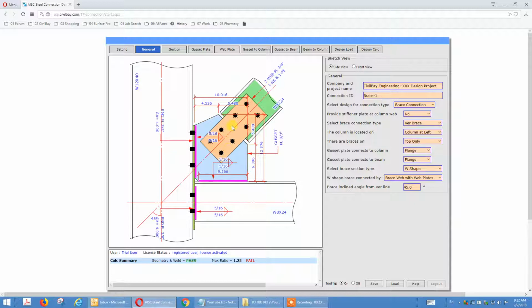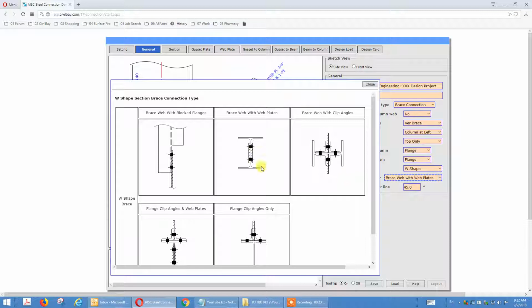This type is normally good for double shear, with double side shear frame. It's good when your brace is slip critical connections. Okay, you double the slip critical connection capacity because it's double face of interface plate. Okay, friction on double sided. That's the second type. This one.